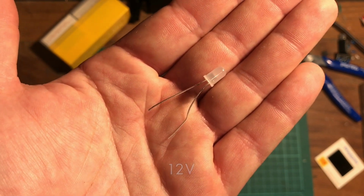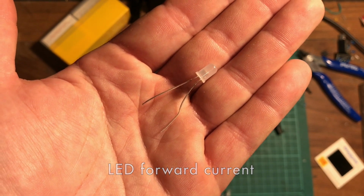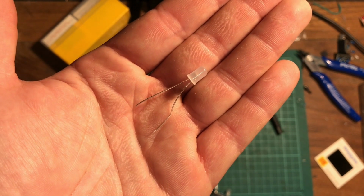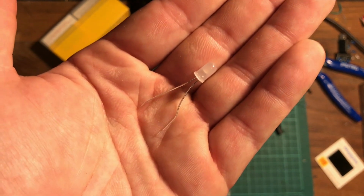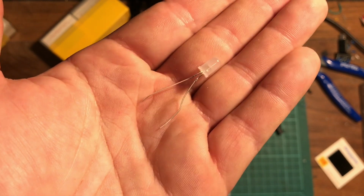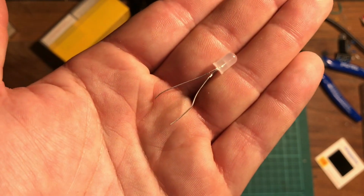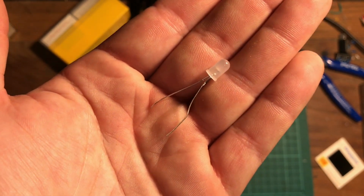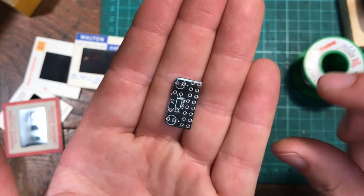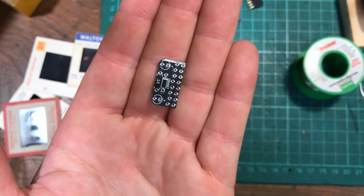All you have to do is use Ohm's law, and you can find Ohm's law calculators online. You put in the voltage, then you put in the maximum forward current that is on your datasheet, and then it will tell you the resistance, and you don't want to go lower value than that. So just get the resistor of the next highest value that you've got and stick that in, and that will give you the brightest light without blowing it up. I'm going to use 220 ohm resistors for mine. It also has a diode there for reverse bias protection, just in case you plug it into the power bus the wrong way round and it breaks your LED.